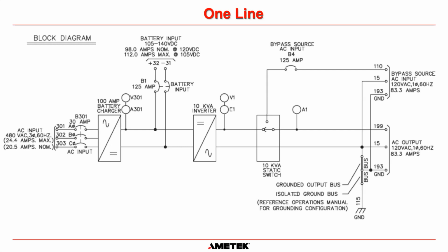Now for our DC connection, obviously it says here that this system, and it will depend on what kVA size your system is, the max current that you're going to see is 112 amps. So you have to size your cables to handle at least 112 amps.